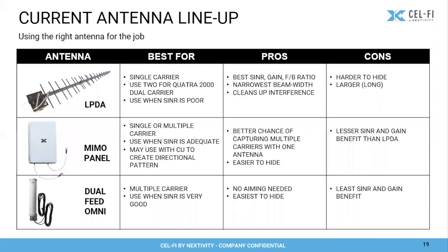Do the measurements. Yeah, so I guess more specific, how much elevation above the rooftop are we talking? Oh gosh. I've seen so many different things on skids. I wouldn't have something sitting 2 feet above the rooftop and 20 feet in from the edge, or 10 feet from the edge. I wouldn't do that. I'd have it at least up around 4 or 5 feet with say the LPDA antenna, just to get away from other structures on the roof and not impede that parabolic space that we're talking about.